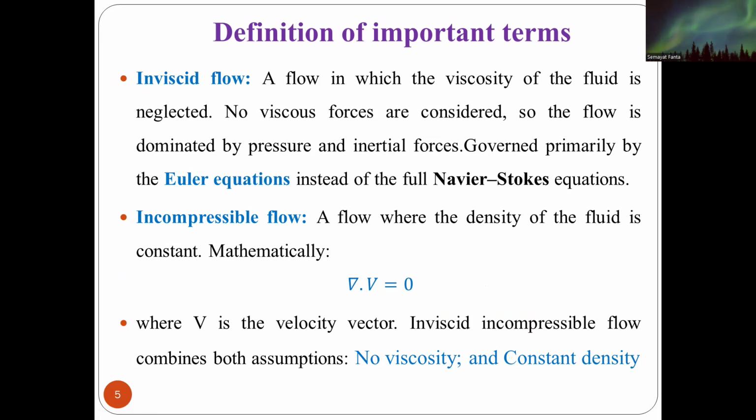Inviscid flow is a type of fluid flow in which the viscosity of the fluid is not considered and is neglected. So no viscous forces are considered, and the flow is dominated by pressure and inertial forces, governed primarily by the Euler equation.